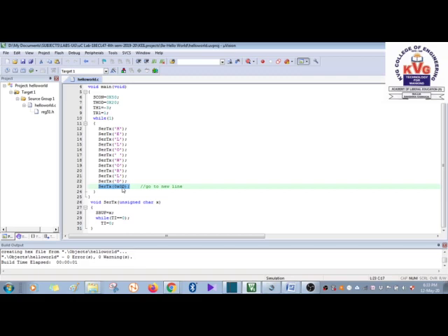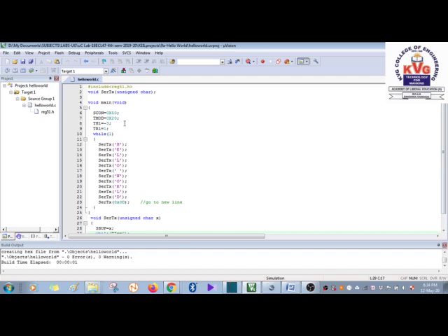0D is the number which is given to start on a new line. So that is why you will have hello world, new line, hello world, new line, hello world. So it will repeatedly display hello world on a new line. Okay, so that is a very simple embedded C program to send the characters hello world through the serial port and display. This is the transmission part. So we'll just run it here. We'll also run it on Proteus and see.